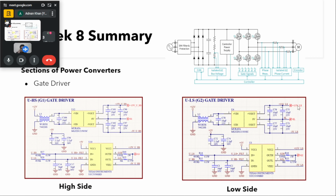And here you can see we will be having a Murata gate supply, which has an input of 12 volts, and at the output they'll give a plus 15 and minus 3 volts in order to drive these devices. We'll be having a single isolated supply for these low side switches, because the sources of these devices are at a common potential.